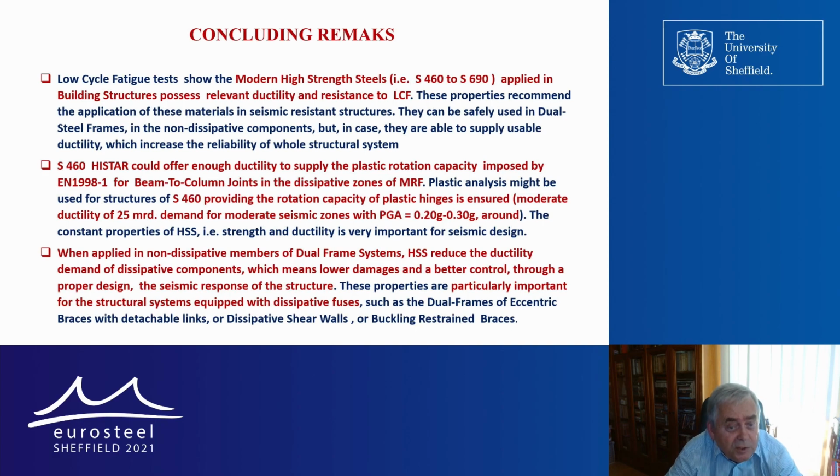When applied to non-dissipative members in dual frame systems, high strength steel reduces the ductility demand of dissipative components. This is another very important conclusion, which means lower damage and better control through proper design of the structure.